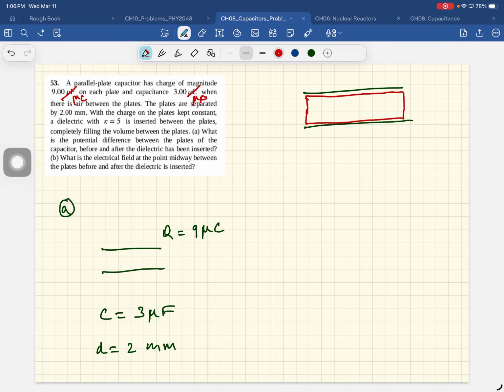Yeah, it's an insulator. That's okay. It has no free charges. So it's doing multiple things. Like Lee said, it increases the capacitance, it decreases the electric field, it provides insulation, prevents these plates from touching each other. So it provides mechanical support, it increases the capacitance, it lets you store more energy and all that stuff. Okay.